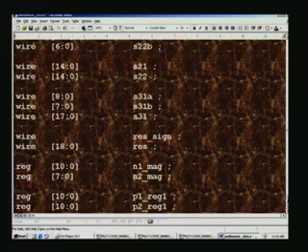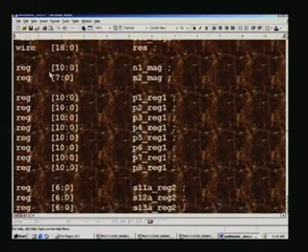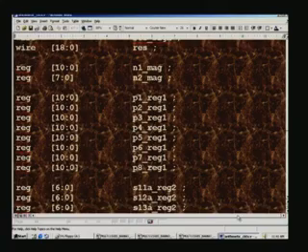We are looking into the Verilog coding of the multiplier algorithm, and we are multiplying two numbers of 11 bit and 8 bit, say n1 and n2. We have also seen the definition of the various IOs of the module mult 11s by 8s, and we have also seen the wire listing here, and right up to this we are looking into the different wire and reg declarations.